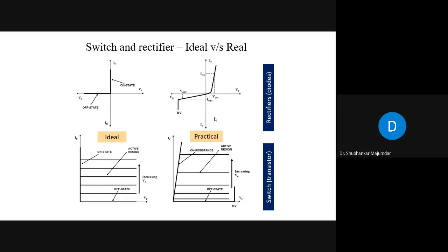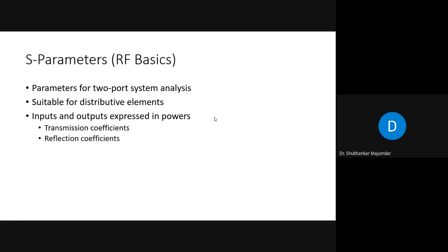These all are basic in nature, whatever I am telling. Now, as we are going into RF circuit design, we have to know about the S parameter. As we are dealing with RF circuits, we cannot see the voltages or currents by simply shorting and opening, because the input frequencies are very high. At that high frequency we cannot short and open.